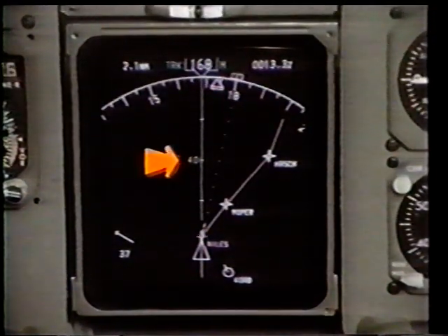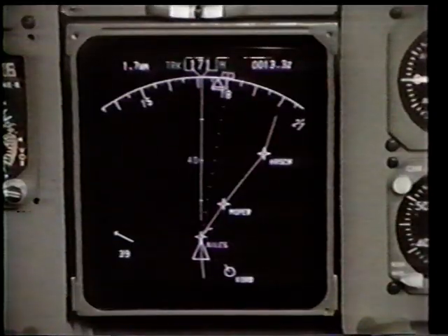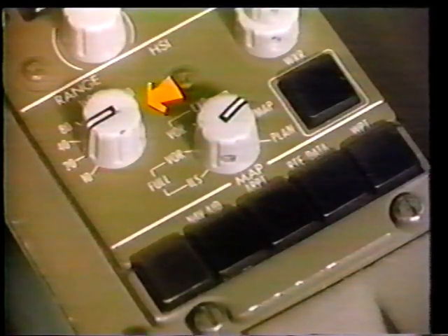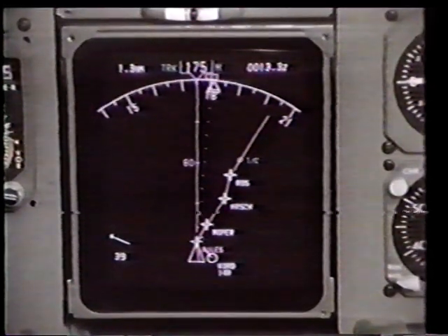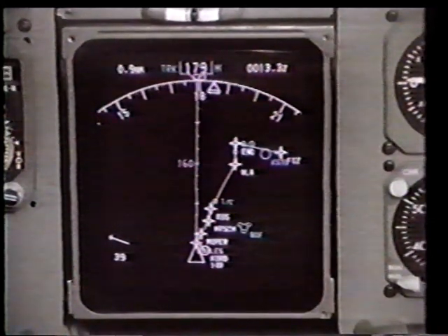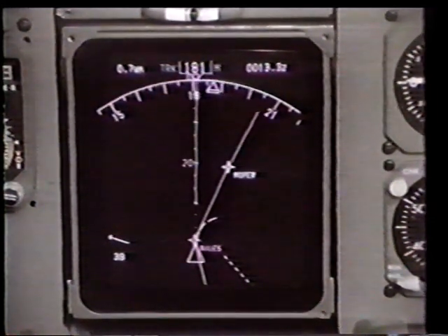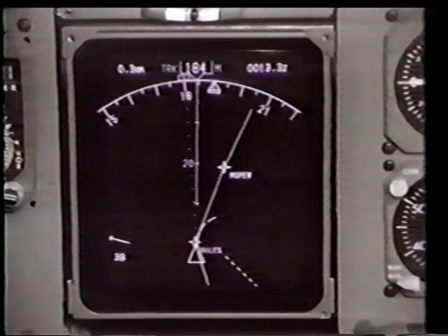The number at the midpoint of the track line represents 1/2 the map display distance coverage as selected by the range selector on the EHSI control panel. The range can be varied from 10 to 320 miles. The flight plan defined waypoints are shown as stars. A solid line representing the flight plan route connects each waypoint.